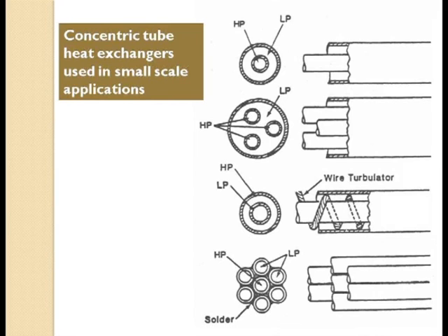version over this. Then you can also have heat transfer between several fluids having soldered tubes. This tube is soldered with this, is soldered with this. So heat transfer between tube to tube will be much higher because of the solid contact between this fluid and this fluid. Not only solid contact, you have a good amount of joining between this tube and this tube. Therefore heat transfer is increased. But however, these are for smaller systems, and relatively less efficient heat exchangers can be made out of this configuration. Not very efficient effectiveness, and not very compact either.